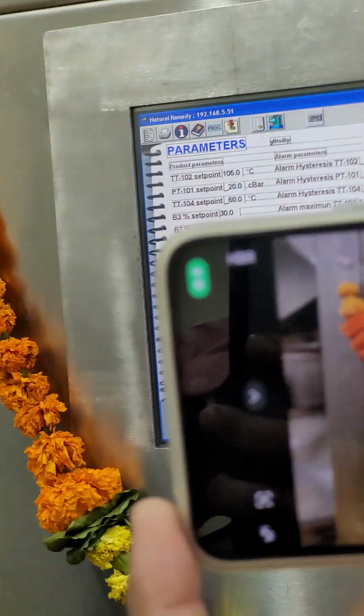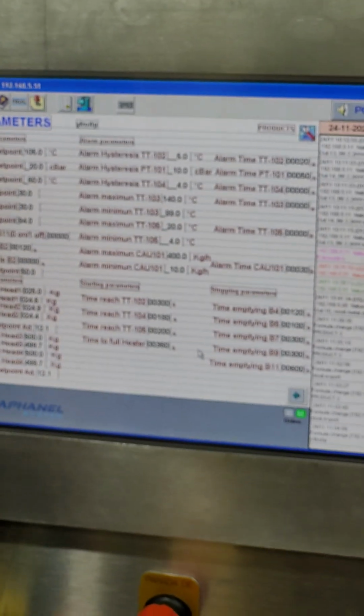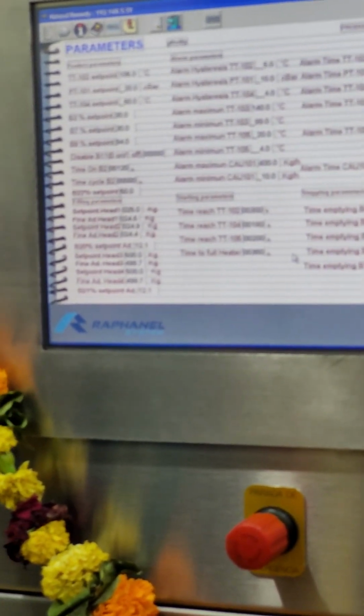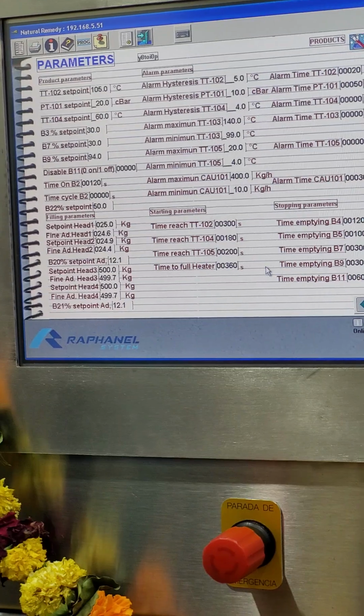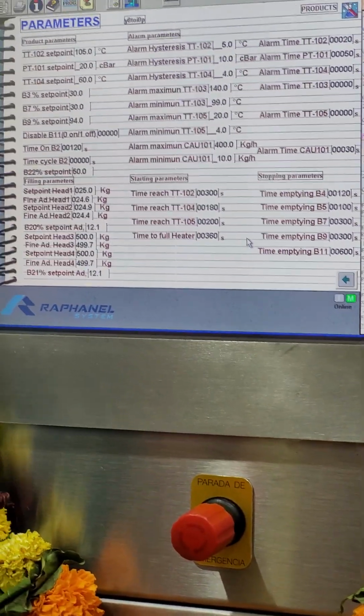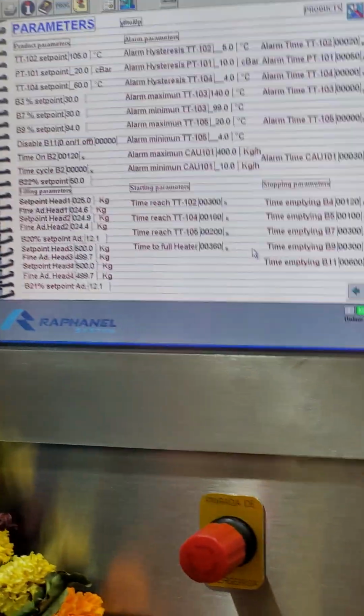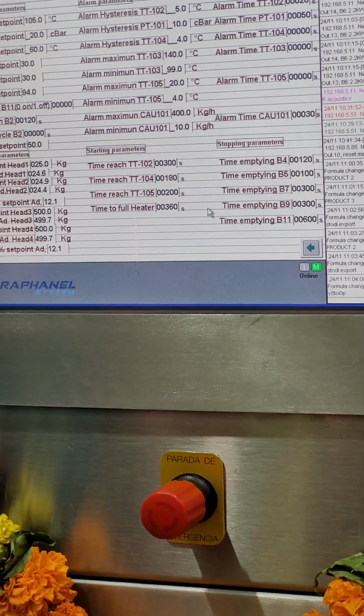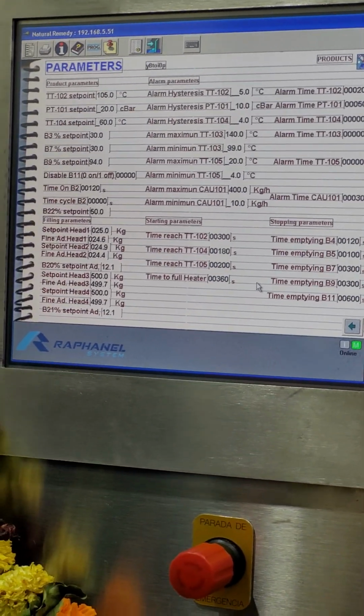I got it. But it depends on the material. Powder is different, seeds are different, whole bigger pieces of material are different. The set point is not standard for all. If you always use powder, it flows, fluidization, and then moves easily. If you have big pieces, air won't help, then you need more speed. But if you come back to powder, in order not to fatigue the materials, reduce the speed as much as possible. Perfect.